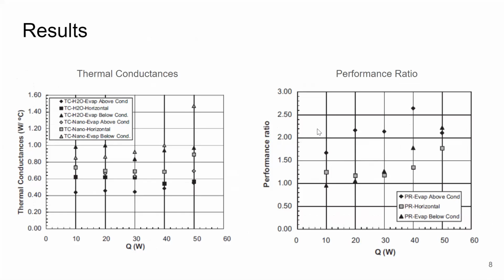Based on the results, we got a thermal conductivity graph. Based on this graph, we were able to see that the nano had a higher conductivity compared to the water with the lower temperature. We believe due to nucleation sites, more solids were thrown into the mix of the fluid and the bubble generation intensified, especially in the high heat loads. Based on these loads, it created a lower thermal conductivity for the vapor than the liquid. Since there is a lower conductivity, there is more vapor present for the pulsations. With the more pulsations, it gives us a 15% increase in thermal conductivity compared to the water.